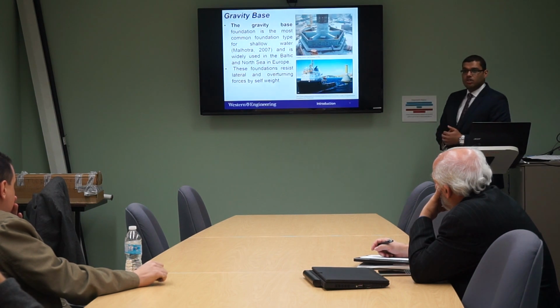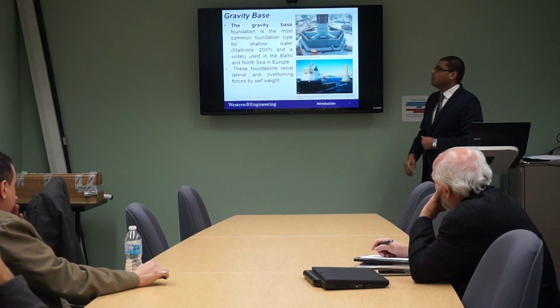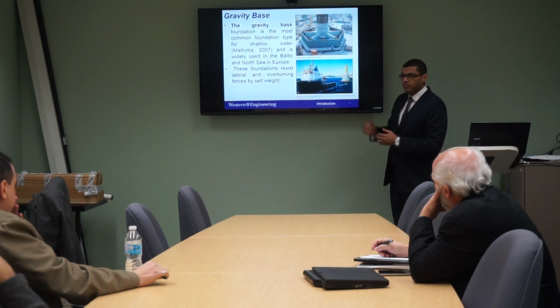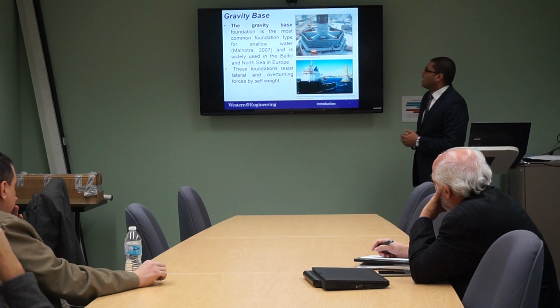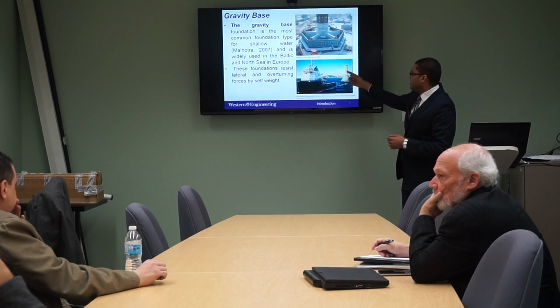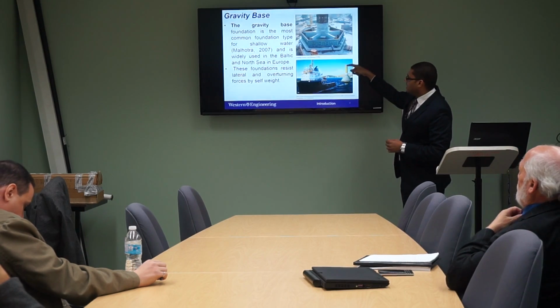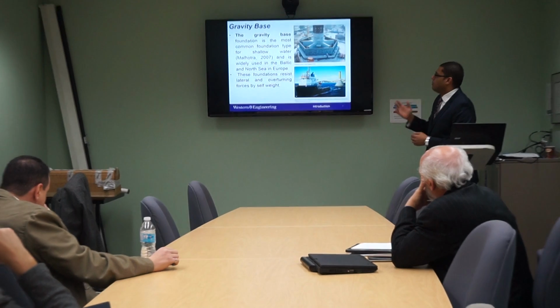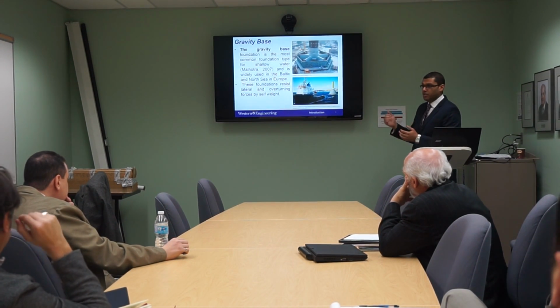For gravity-based foundations, we have different types of gravity-based foundation systems with different shapes. The main thing here is that it is constructed onshore, then transferred offshore to be erected, to reduce the cost of installation. It can be added here with some surrounding soil to increase its self-weight. It has been used in the Baltic and North Sea, where they have experience with this type of foundation from the oil industry.